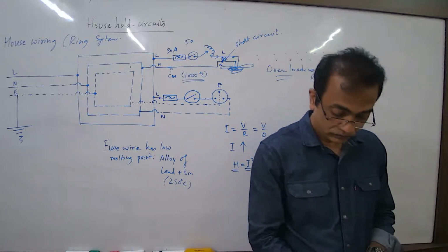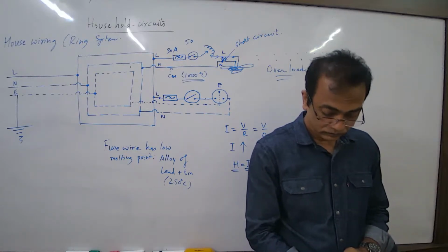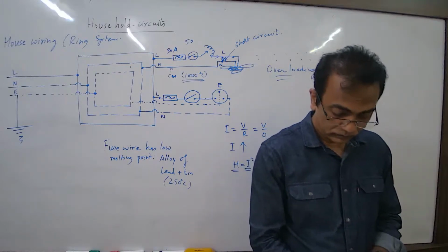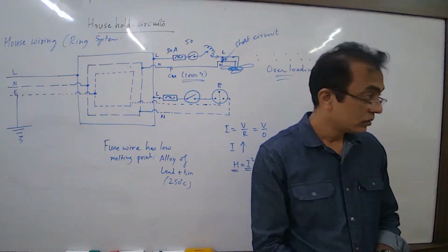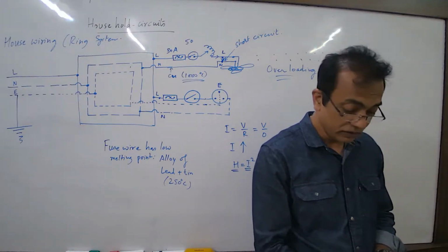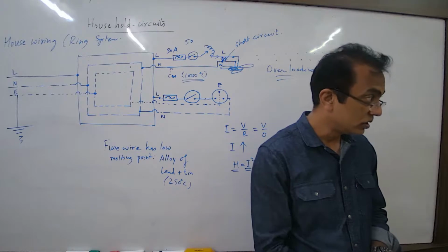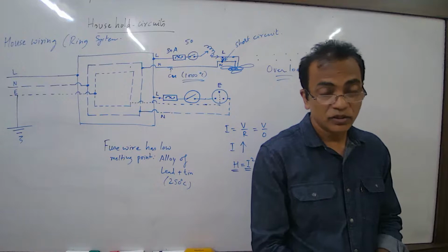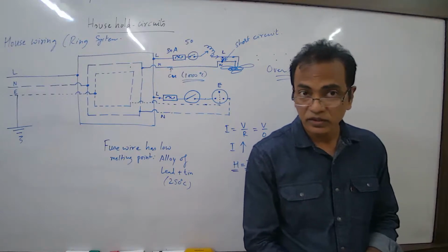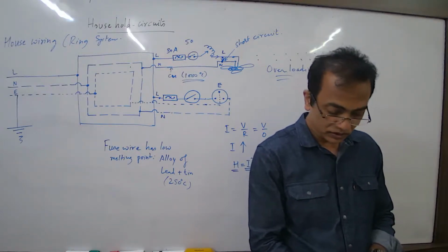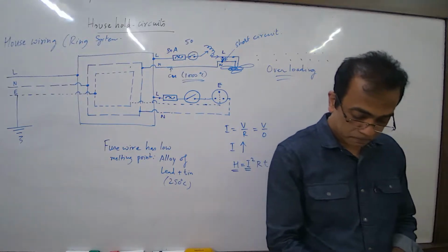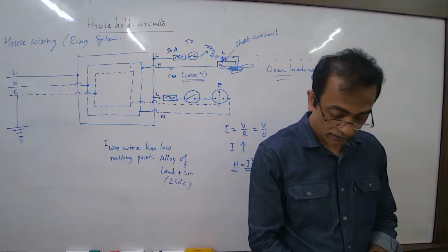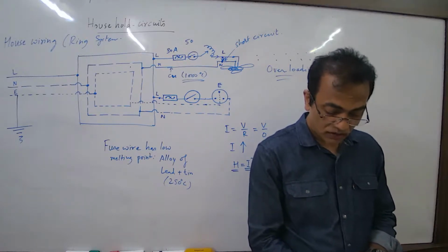First, the voltage of the source gets divided among all the appliances connected in series in the ratio of their resistances, so each appliance does not operate at its rated voltage. Right. So every device will not get 220 volt. It is getting divided amongst various appliances connected in series. Because in your house, what is the maximum potential difference? 220 volt. Okay. Next. Second, on connecting one or more appliances in the same circuit, the resistance of the circuit will increase. Hence, it will reduce the current in the circuit, so each appliance will get less power.